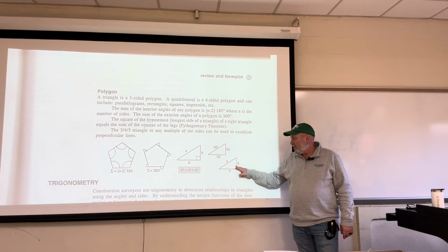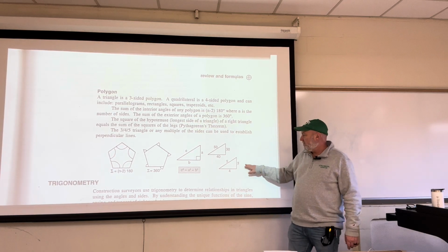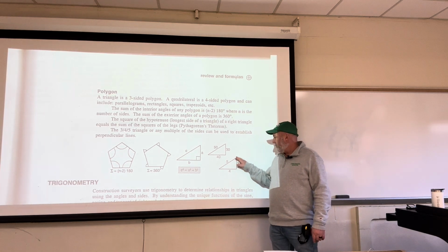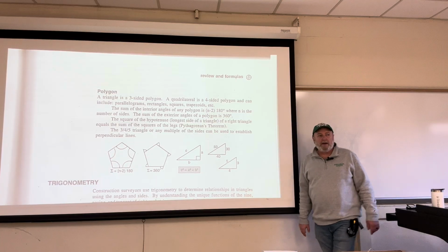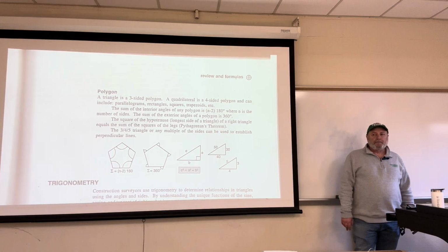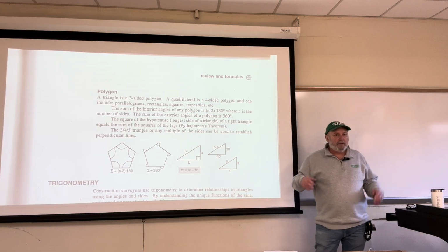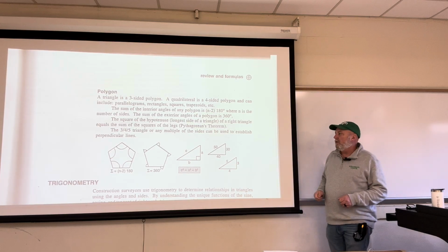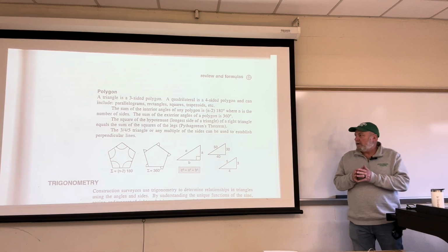If, for example, you measure up 3 feet and measure out 4 feet, the hypotenuse between those will be 5 feet exactly. This is unitless because it is a ratio, so you can expand that to whatever you want in order to create a nice right triangle.